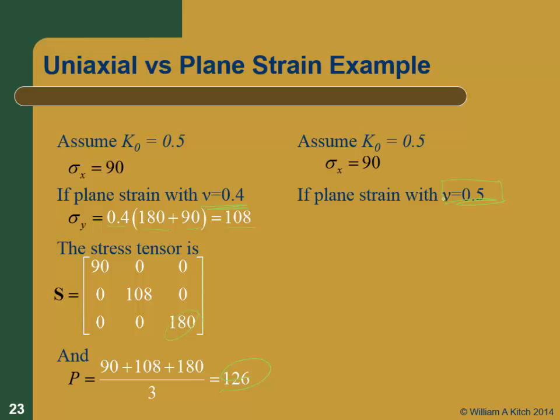So as Poisson's ratio goes up, the stiffness goes up. Notice that the Young's modulus doesn't have to change. You could have a constant Young's modulus, right? And as Poisson's ratio changes, the soil gets stiffer. Well, that's of course, because Poisson's ratio is not the bulk modulus. Poisson's ratio does not relate sigma, the mean normal stress, to the volumetric strain.